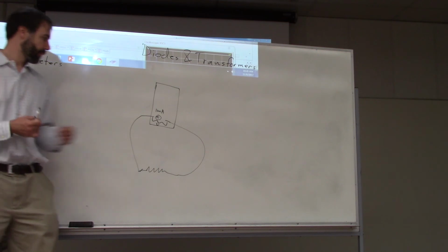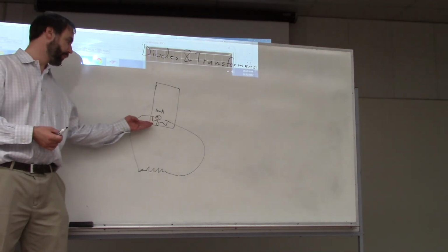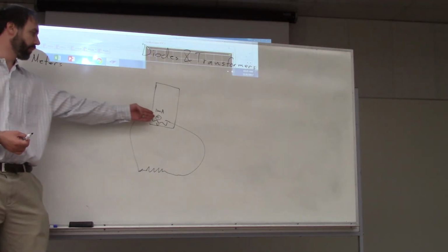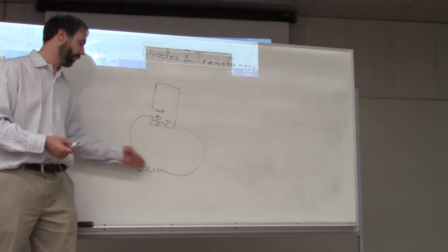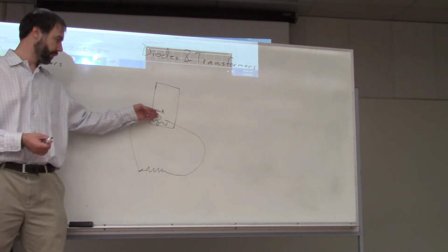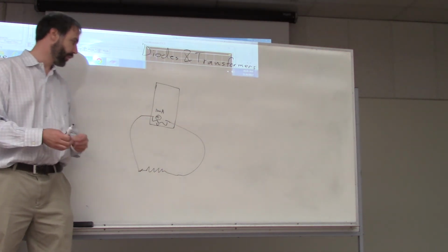So in that case, you're sending the current through both leads, and so you're really measuring the resistance of both leads.